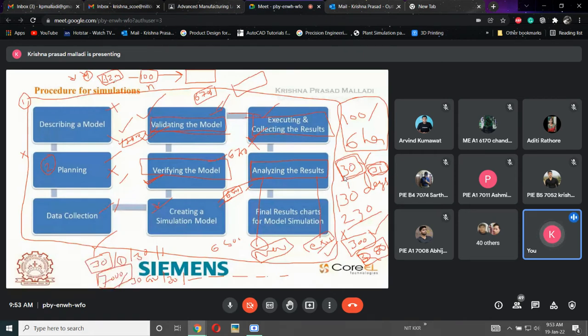Now what is the expected time for this part to come out? 100 missions, each mission having 2 minutes, which means theoretically we will have 200 minutes. This is mission processing time. Now the station has some material handling. For every material handling there will be 1 minute, station to station. Plus 100, so together I am expecting a part after 300 minutes. This is exactly the theoretical value. With respect to theoretical, this is the time I am supposed to expect the part.